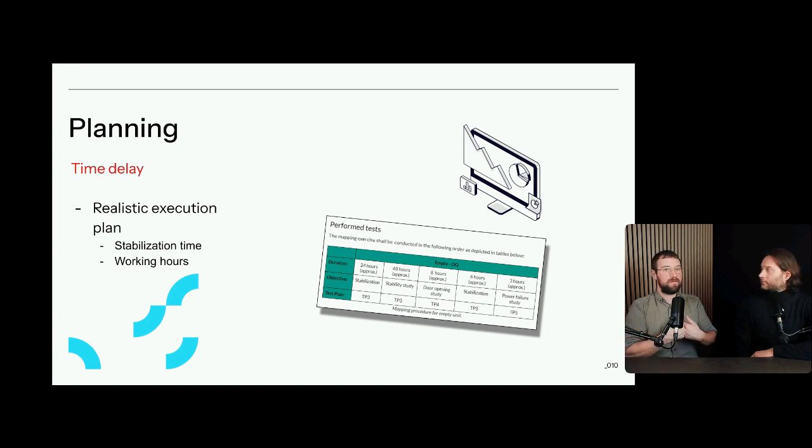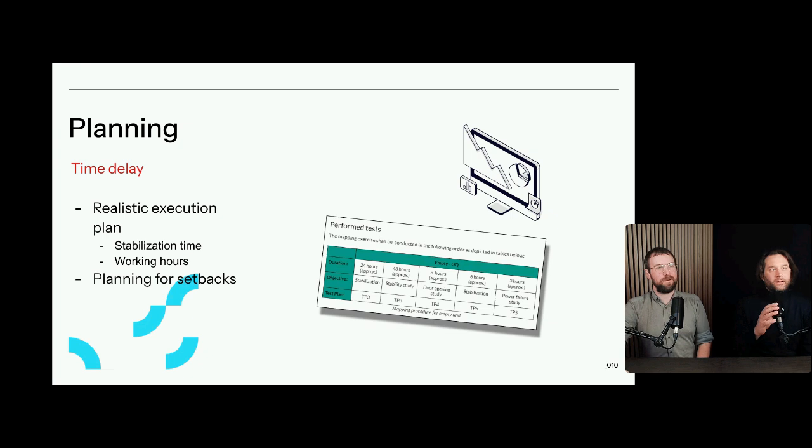If it's a new warehouse, have you planned for the final electrical installations that always need to be done just at the very end? And also, if you've set up a mapping, you might have accounted for 6 hours to set up the data loggers and then start a mapping that should run for, let's say, 72 hours. Well, when you start to take them down again or start your next test, that might be in the afternoon and people are ready to go home. So having a little bit more realistic expectations for when people are working and so forth, that's really one of the key elements.